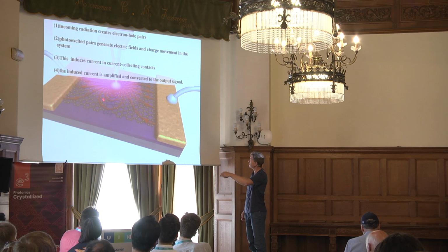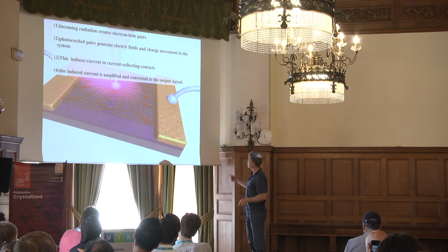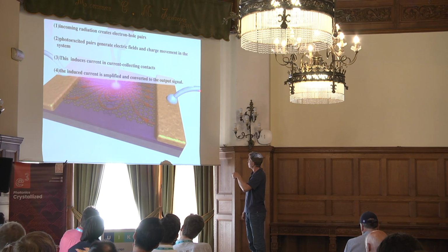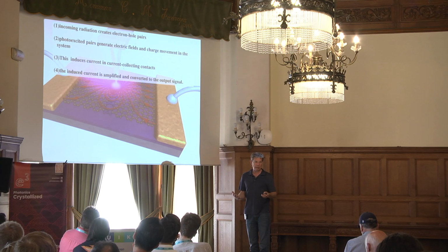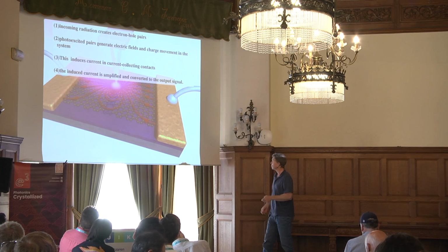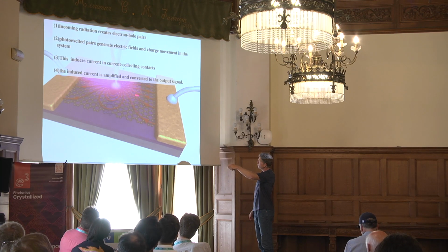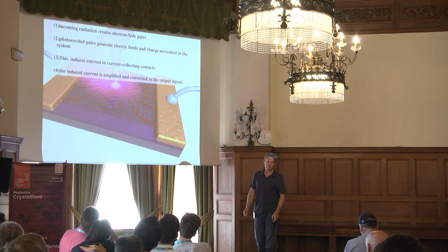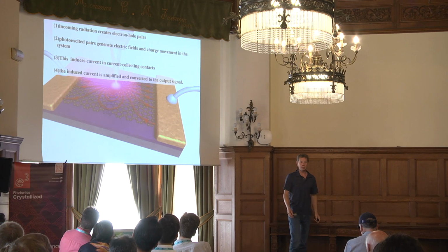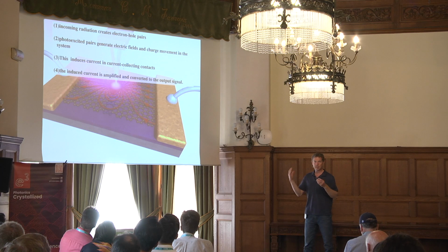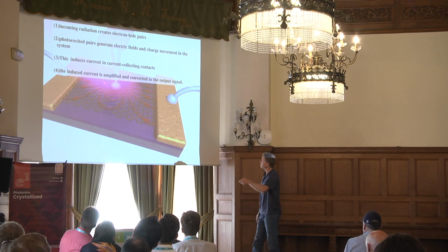Some of these currents start actually just circulating, and nobody knows about those. Okay, I cannot measure them. But some of these currents actually make it all the way to the metallic contacts. And when I measure now the current, just with my current meter, from this contact to this contact, I actually will measure this. Okay, so locally something happens at a scale of like 10, 20 nanometers, but these contacts can really be far away, microns or even millimeters far away, and I can still measure this effect.